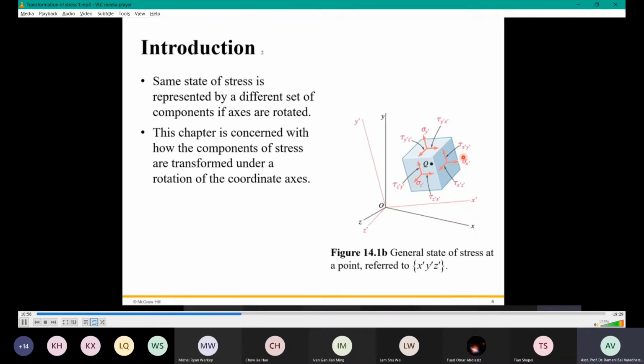When you go to the drawing side, you must remember this. It is totally different from what you did in the transverse loading. In transverse loading, shear force upward is positive, downward negative, and then moment, you take clockwise positive, anti-clockwise negative. Here it is totally different. You have to remember, this chapter is taxing your remembrance. You must remember when you do the Mohr circle because it is defined by Mohr. He has set the rule. He has set the sign convention.